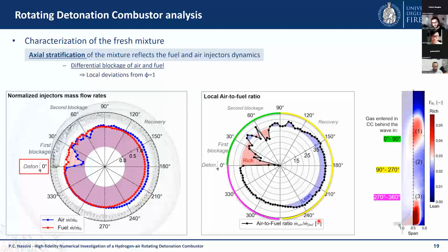And at the end, we should have a roughly stoichiometric mixture in the last 90 degrees, but of course in the last 90 degrees reactants don't have the time to mix. So overall this mixture should be stoichiometric, but the spatial inhomogeneities are preventing us from seeing a white color in this region.